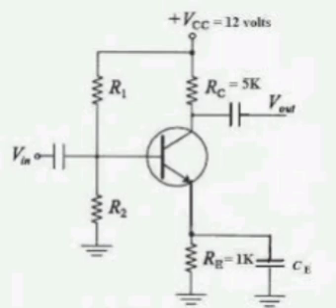The voltage corresponding to each discrete level, the quantization step, is given by delta equal to V reference by 2 power n, that equals 5 by 1024, which is approximately equal to 0.00488 volts. Step 2. Quantization error. The maximum quantization error EQ for an ideal ADC is half of the quantization step size. This represents the maximum deviation that the actual analog value can have from the quantized digital value. EQ equal to delta V by 2, that equals 0.00488 by 2, which is nearly equal to 0.00244 volts.